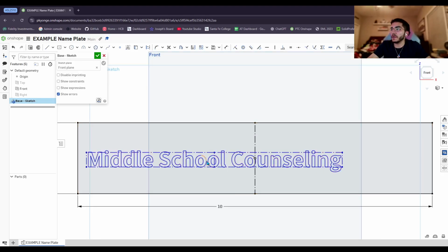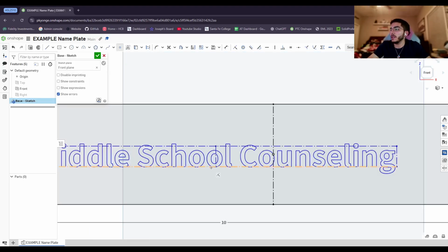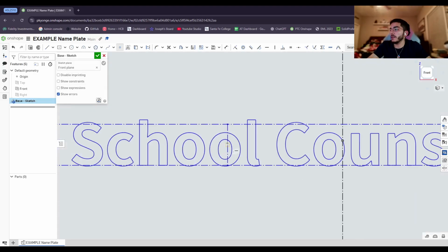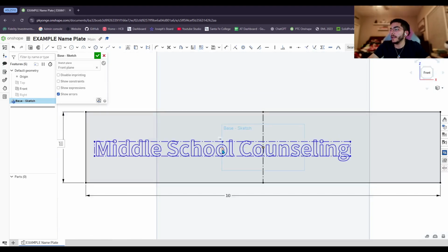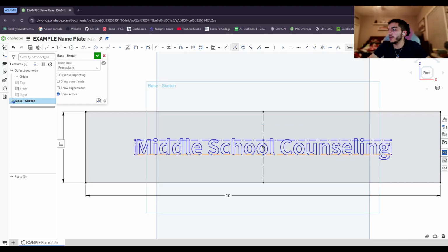What you're going to do is click Shift S on your keyboard, or point, and then click the point in the middle of this line here. Have that point, and then click coincident, or I on your keyboard. And this is a constraint. So coincident means when I hit this point and I click this other point, the origin, it's going to connect the two. So now you can't move it out. It's not escaping now. It connected the two points.